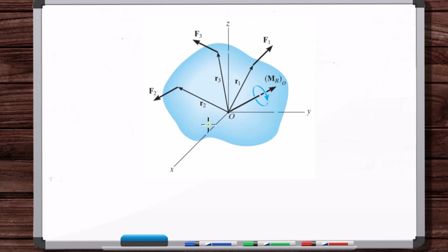But you couldn't say, okay, I'm going to have this point A, I'm also going to calculate a net resultant moment, or just a moment of one of these forces about A, and put a moment here, and we'll have this moment and this moment. You can't do that because that's implying that you've got two F2s and two F3s and two F1s.